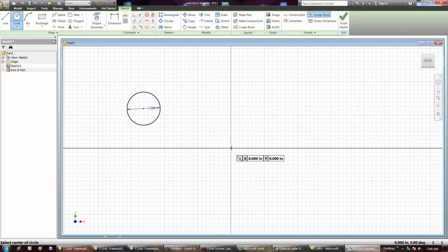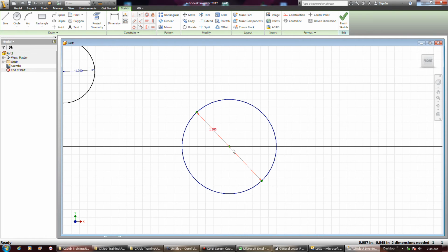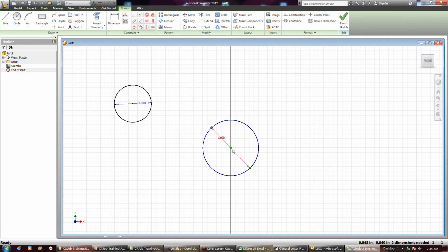But if you create a circle and start from the center, you notice that it tends to align with the axes to some extent. See, it's a little bit sticky. If you start from the center and make it 1.5 inches, you'll notice that the center point is green here, so you can't grab it. Like I said, when it's a green point, that highlights that it's permanently constrained.